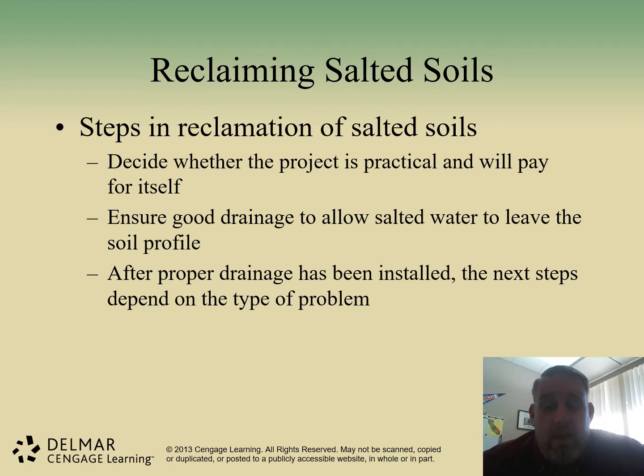If you have a very short root system or you are close to bedrock, then you could have a problem removing the salts from the soil. And then making sure you have good drainage, and if not, then you need to install proper drainage to allow the salts and the salted water to go somewhere.